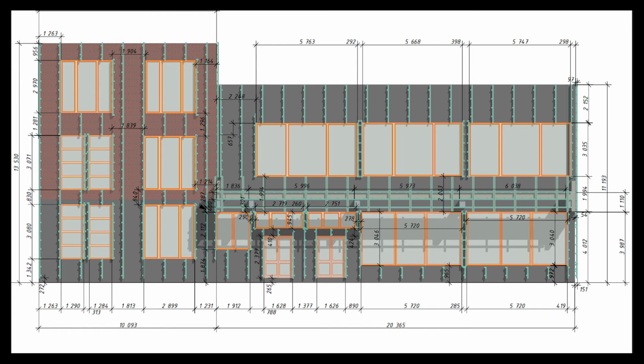Whatever people would tell you, like we don't need a design, they lie. Regardless how experienced they are and how many buildings they did, you cannot make a ventilated facade without complete design, and all the panels in it should be as precise as 5 millimeters. So imagine the amount of work. If you're doing it without a complete design and precise panels, you will suffer greatly. The losses would be so huge, you will regret 10 times that you did not order the complete design.